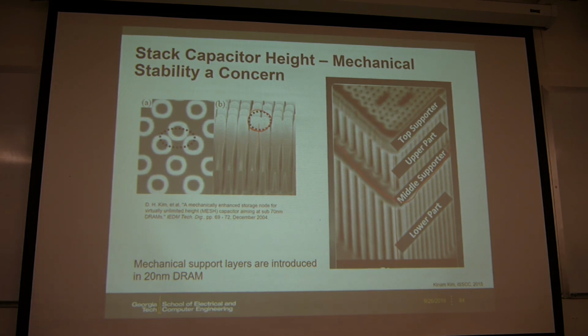Those equipment companies are really making the money out of those etching tools, especially from 3D NAND. 3D NAND is even more difficult than this one to etch, because here you just etch the same material. Let's say you have the dielectric, and then just dig some hole into that dielectric. 3D NAND, I think the next lecture, or we may revisit this later. In 3D NAND, you have metal and dielectric, different materials in that stack, and you want to etch through different materials. That's even more challenging. This is why here you only have one material to etch.